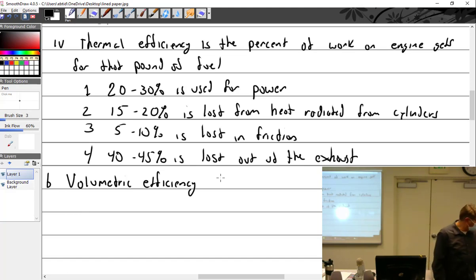But this thing's moving up and down at a rate of 2,000 revolutions per minute. So that piston's moving really fast. By the time the piston's coming down, the air says, oh, we're supposed to go in. The air starts to go in. The piston's already turned around. It's pushed. Oh, now it's time to go the other way. So it's not filling up the cylinder by any stretch of the imagination. It's only partially filling the cylinder.